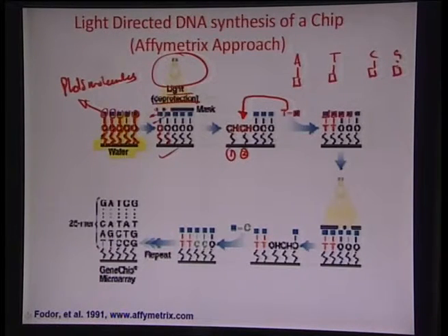Okay. So once this is done, you can again use a different mask with an exposure in two other areas or two other sites to open the linker layer again by decapping these two capped molecules or photomolecules, and then you are again doing the same chemistry wherein you have this OH bonded to this area, and then maybe in this case you are applying a cytosine coated with a photomolecule, so that it comes and bonds to these two sites here which have been opened up, and after bonding it again gets covered with this small capping molecule.